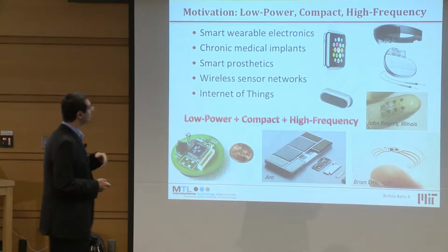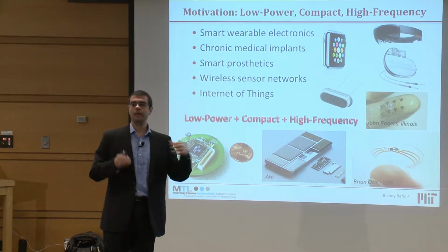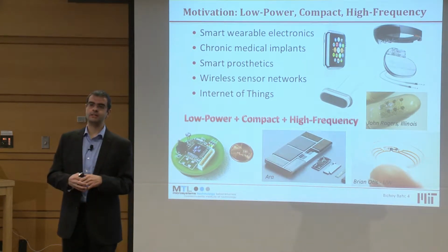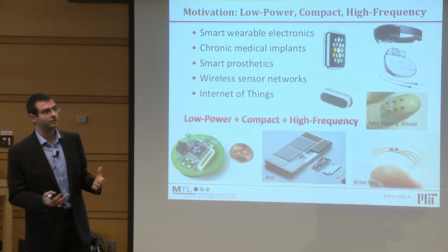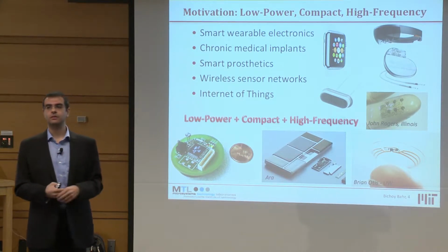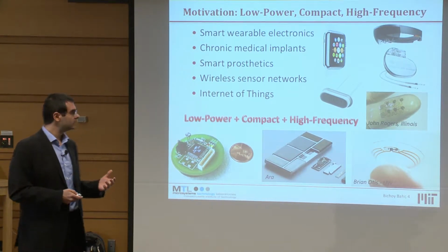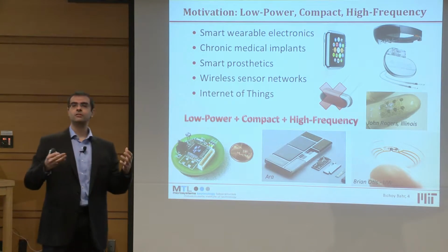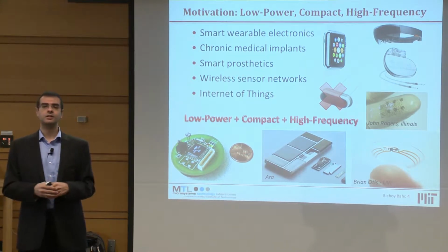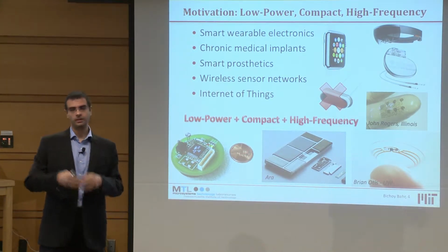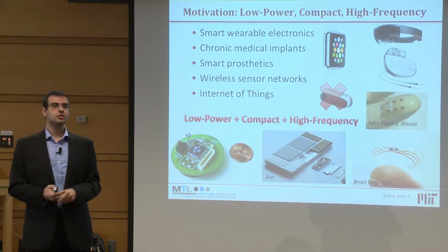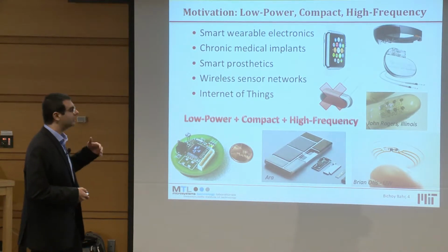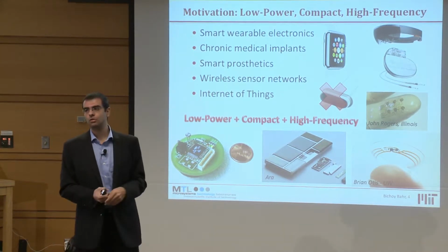In the past decades, we have been relying on quartz crystal to act as our resonator, our mechanical filter, and we used it for local oscillators. But as we can see, its form factor is getting very bulky. It requires an extra pin on each chip. It takes space on your PCB. So it doesn't really fit very well in these new applications that we are talking about.